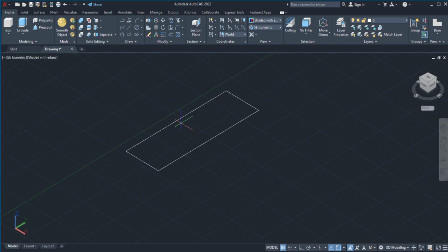Okay, so that is where your right plane will sit. From there we break this to make it appear like a single line. Select object, enter. We have broken it so that we can offset to get the center of some circles that are there in the right plane.